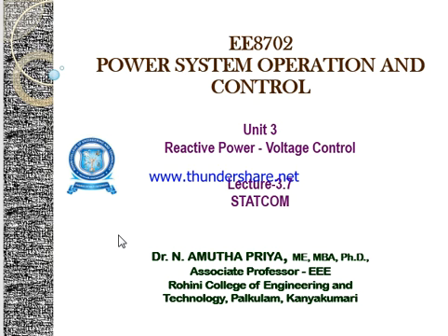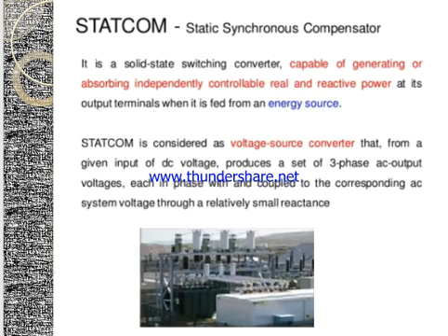We are discussing the course Power System Operation and Control, and in this lecture we will discuss STATCOM. STATCOM is nothing but the static synchronous compensator. It is a solid state switching converter which is capable of generating or absorbing independently controllable real and reactive power at its output terminals when it is being fed from an energy source.